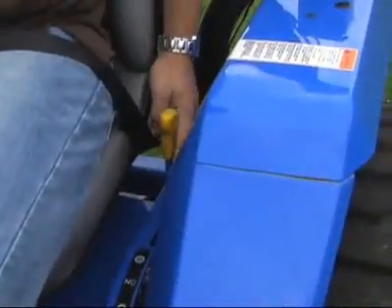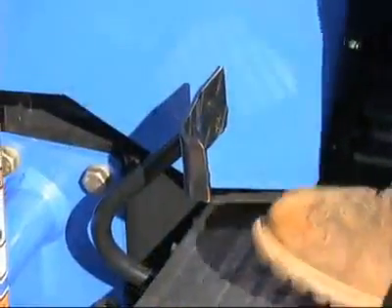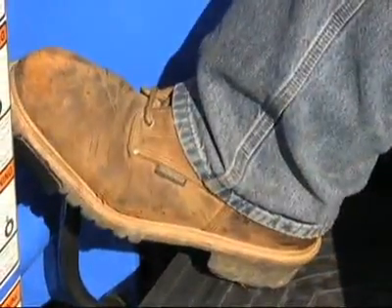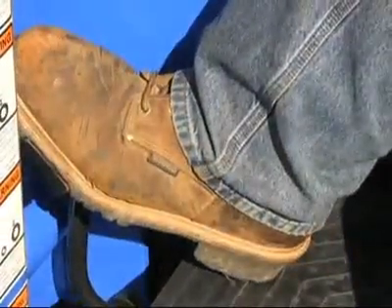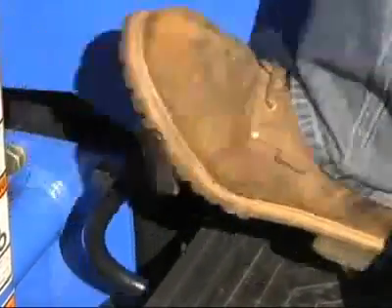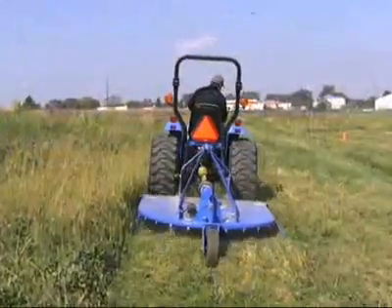When you're comparing compact tractors, you'll hear about 3 different ways to control the PTO. The most basic option, called a transmission-driven PTO, combines the transmission and the PTO on a single master clutch. With this system, the PTO and the transmission are engaged or disengaged together.